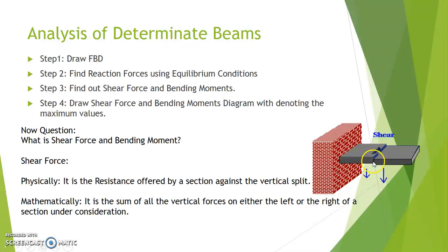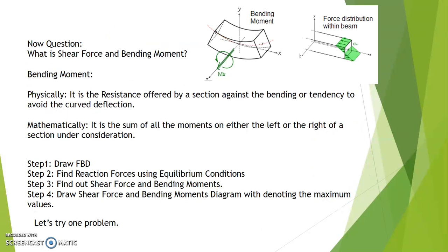It means it is splitting parallel to each other. So mathematically, shear force is the sum of all the vertical forces on either the left or the right of the section under consideration. Either the left or the right: you will consider only all the forces acting on the left, or all the forces acting on the right. We will see one example, then the mathematical expression will become much clearer to you.